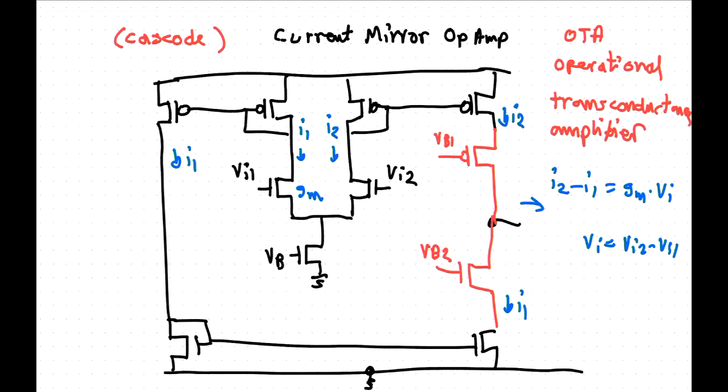The output resistance we get here, looking up, is going to be something like rds for the top transistor times gm rds for the cascode transistor. And then the resistance we get at the output is the same resistance looking down here. So that's also rds times gm rds, if all the gms and rdss are the same.